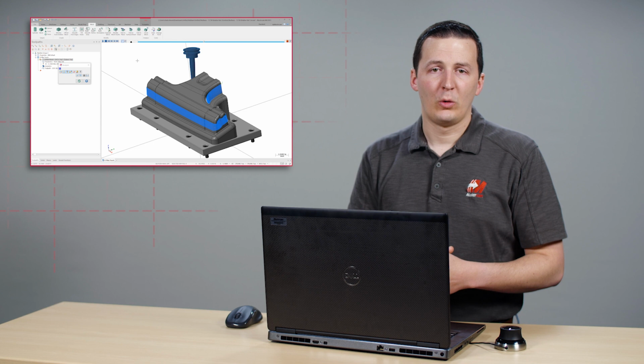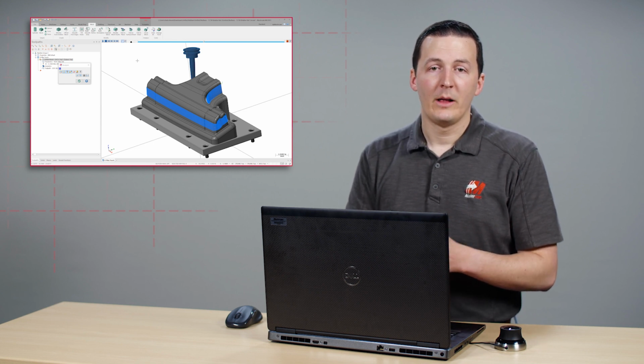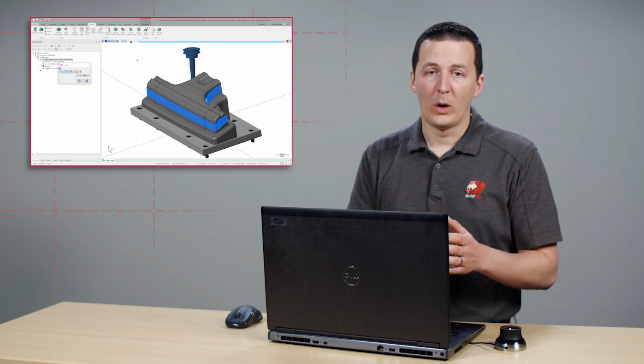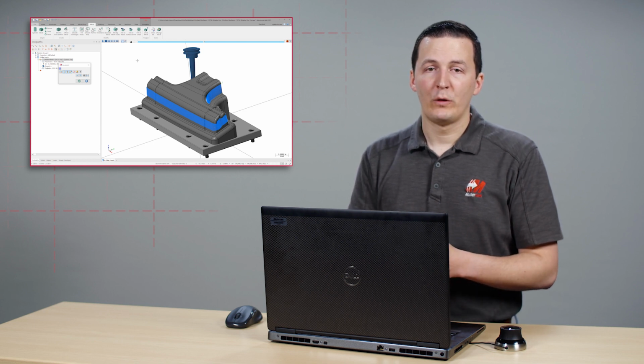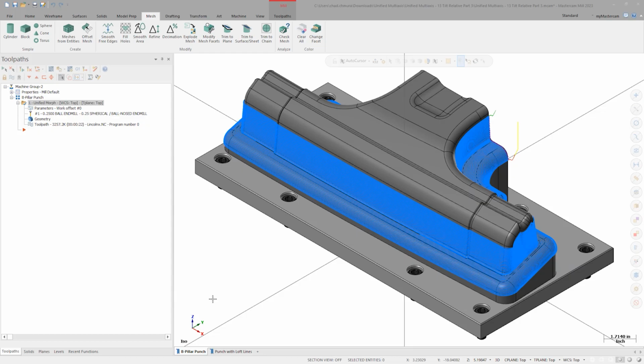Lines tool axis control is an effective, time-honored strategy for controlling tool orientation. The biggest problem with this method, however, is the fact that each one of these 30 lines was manually manipulated one at a time until the toolpath could run safely. Even though the resulting motion is great, creating the input geometry is far from efficient. This is where tilt relative to reference surface comes in.